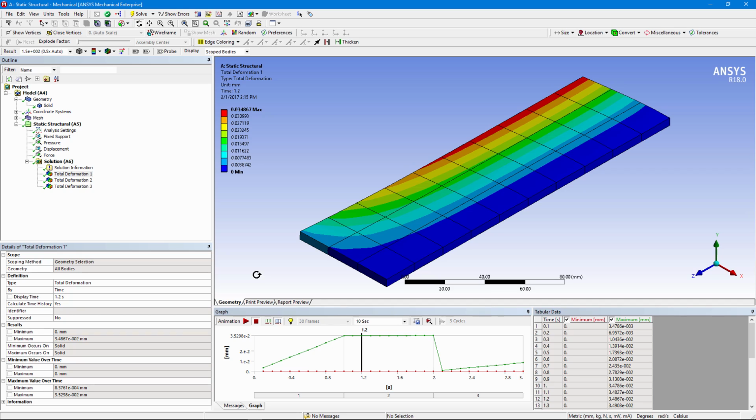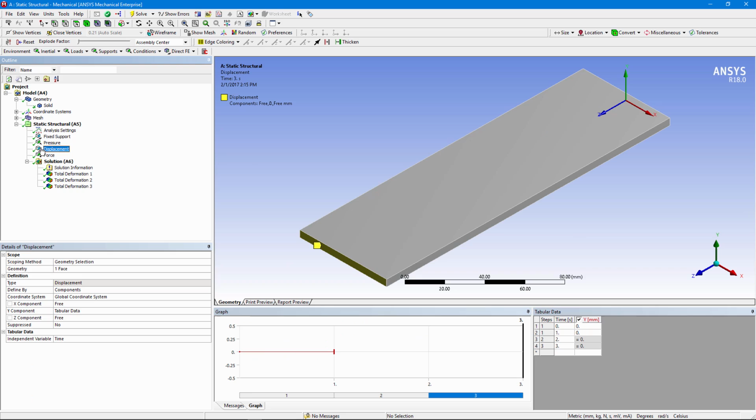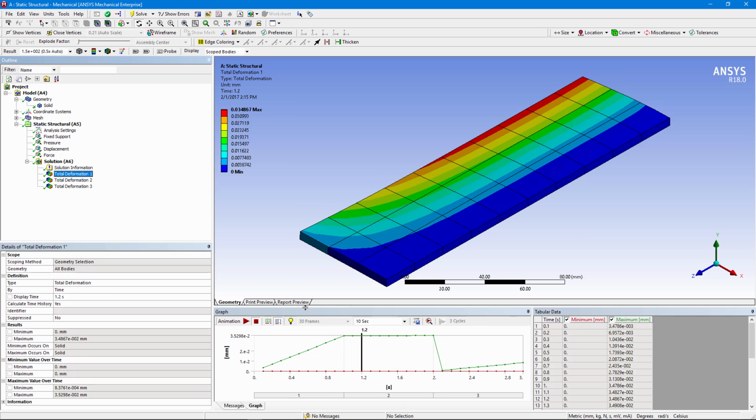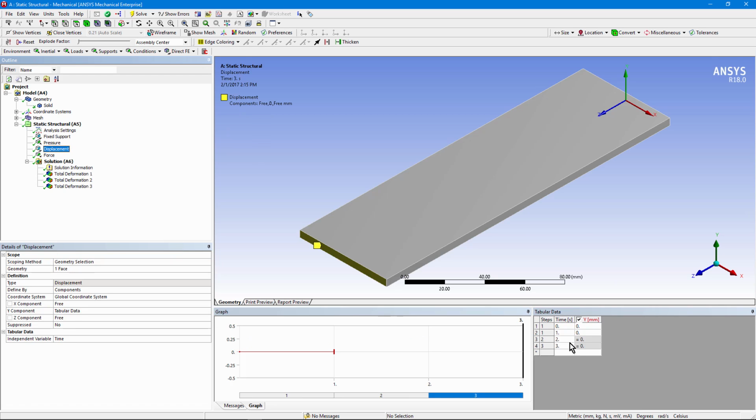If you were running a transient analysis, this was just static. If you were running a transient analysis and you want a displacement constraint like this to disappear, in the transient run, you'll want this time interval for the load step where you deactivate it. You'll want this time step to be a very small time step in real time in a transient if you want it to disappear very quickly.